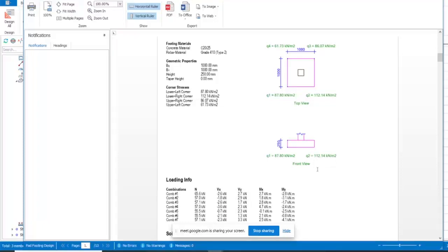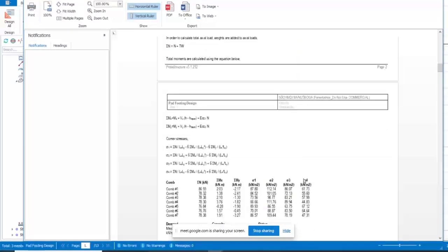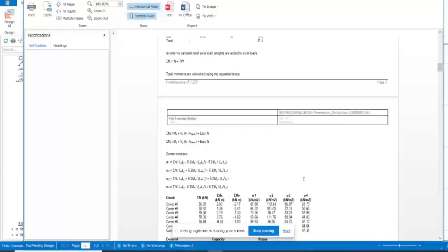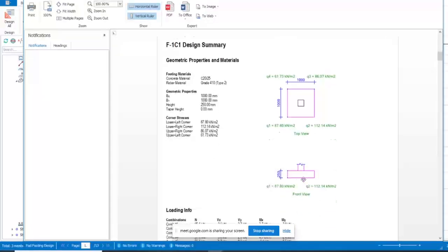Now there is a relationship between the depth of your footing and, okay, let me just ask a question so that I would be straightforward. There's an effect that your column tends to have on the pad base, and that effect wants to tear it apart, wants to cut it along a plane. What's that effect? Most likely punching. Punching. Exactly, that's the word.